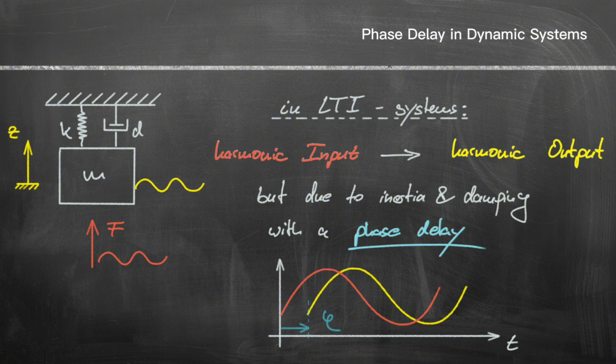At resonance, the phase shift is 90 degrees, and this is critical because, as can be clearly seen, the force occurs exactly at the moment when the velocity of the oscillator is at its maximum, and therefore the system is excited most strongly, and the energies superimpose in a maximally constructive way. In general, it can be stated that the faster the excitation, the more phase delay occurs in the system.